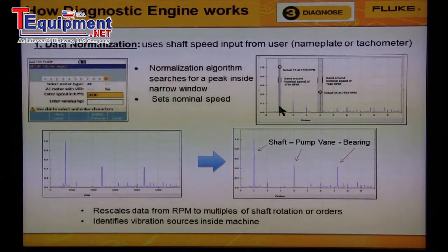This is seen on the graph on the right. The largest vibration typically comes from the large, heavy mass of metal rotating at, say, 600 RPM. In the graph on the bottom left, we see a peak at 600 RPM, a peak at 2400 RPM, and a peak at 4500 RPM.